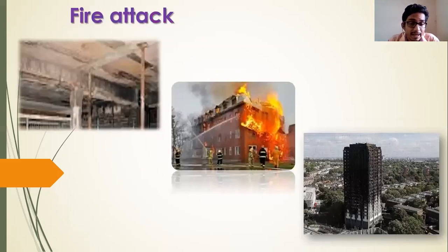Fire attack, you can see, is a step-by-step process. The deterioration that happens in a fire attack is a step-by-step process. First, when the fire touches the surface, the concrete starts losing the moisture from its surface, which will decrease the density and also create a problem in the structure. And slowly it goes inside the concrete system, step by step.